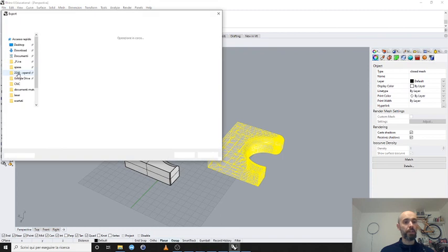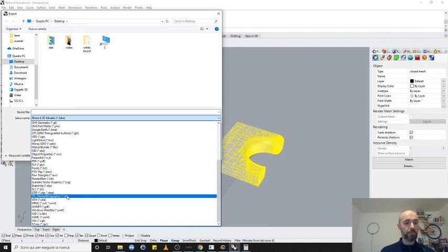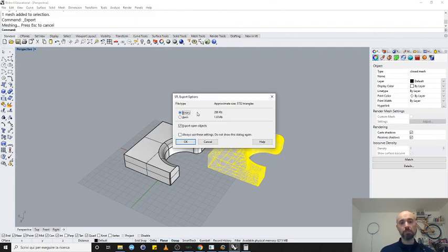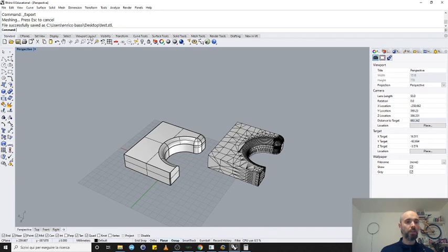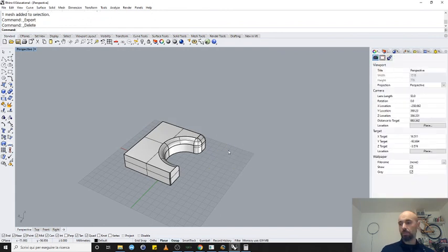You know, export selection, you select an STL file, save it, and you get your object. It asks you how you want it written. This is just the way the STL file is written. We'll get to this when we speak about 3D printers, but it doesn't matter really. So pick the one that is lighter, the binary one, and you got your file saved.